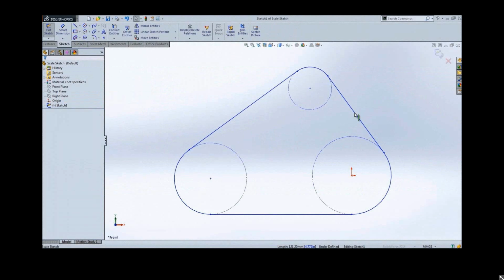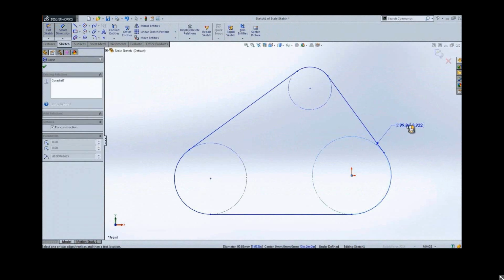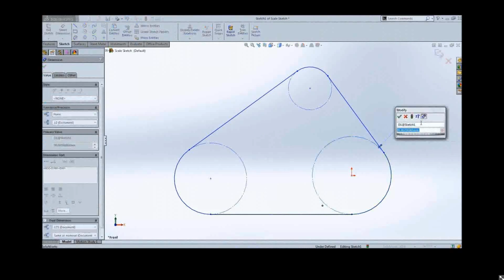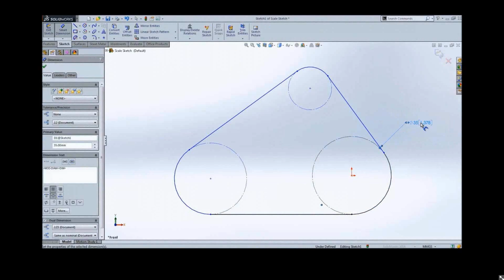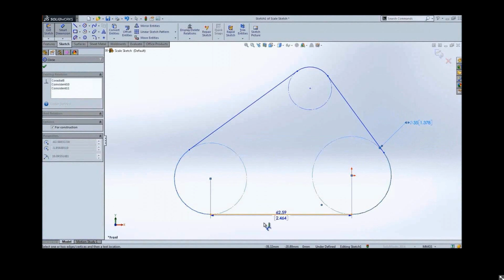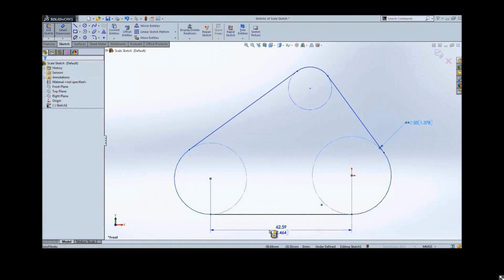Basically, when you create a new part, generally you sketch out the shape of the part that you want, and then you add a dimension. But usually if you added a dimension, it would scale up that certain entity, and your sketch would get really large and maybe blow up a little bit. So what they've done is completely eliminate that, and when you place the first dimension in the sketch, SolidWorks will automatically scale the entire sketch to preserve the size and the position of all entities within that sketch. So you're not going to notice anything, but it's scaling the entire sketch for you.